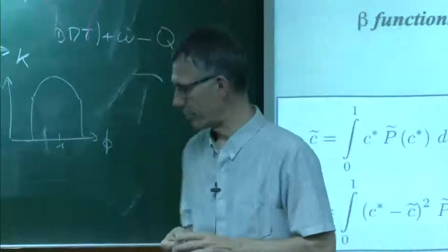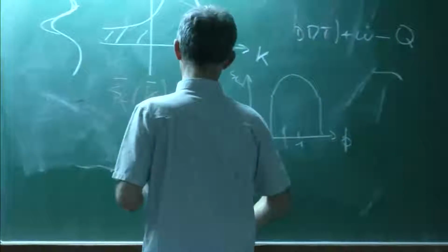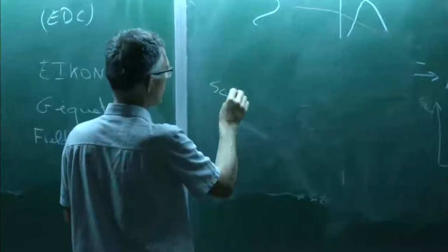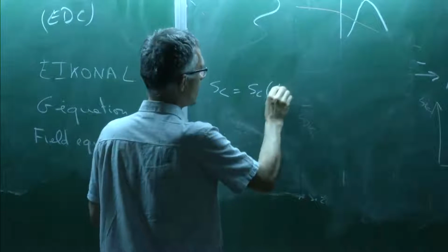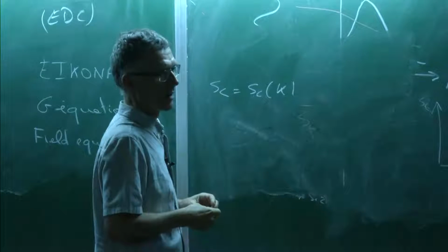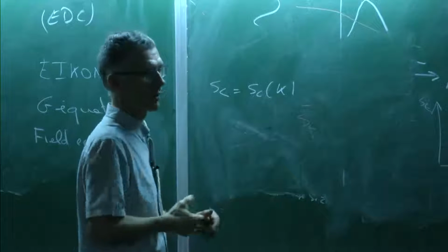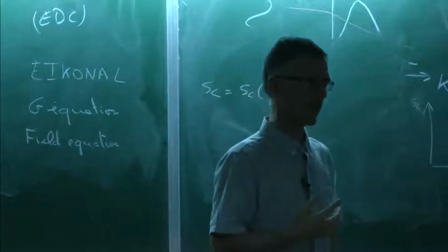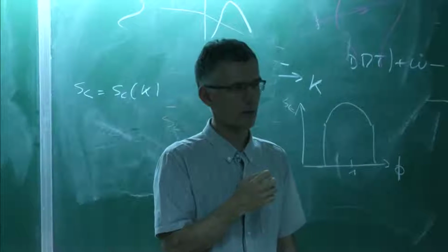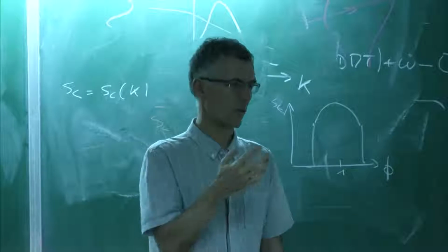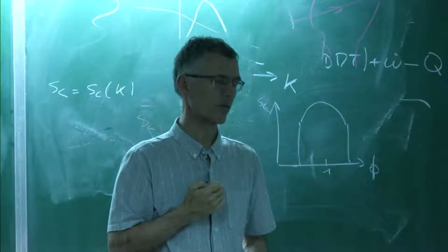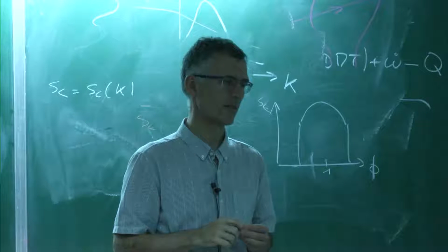Some people tried, for example in flamelet models, what Santanu just asked for, which is they give a model for SL as a function of stretch. So they say if the mean stretch is too large, then there will be quenching. You can do that. But honestly, I think it's very difficult to capture quenching in a RANS code because first you have to identify what's the mechanism leading to quenching. I don't know which configuration you're talking about, but in most cases, one just doesn't see those things. I don't believe it can be done easily.